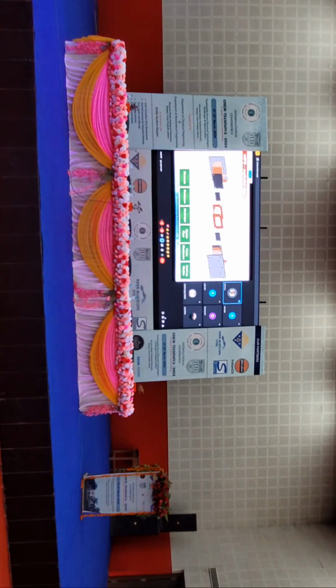Now this is the exploded view of a flow battery of a single cell. You can see this is the end plate. There are a lot of components, like graphite plate, current collector, flow frame. Then this is the graphite felt electrode, on which the reaction happens, different gaskets, separator, and then again the similar set on the other side.